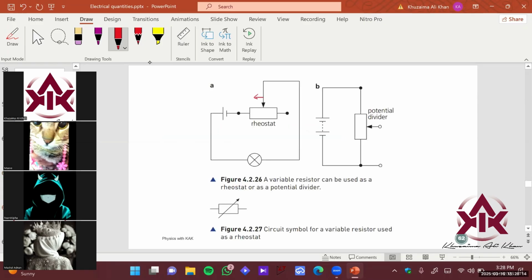So if you move it left, let's say the max resistance it can offer, if my contact is here, is 5 kilo ohm, right? And the minimum resistance, let's say if the slider is over here, becomes basically 50 ohms, right? So we have a range of resistance which it can provide, that is 50 ohms to 5 kilo ohms, right? That is how the rheostat works, right?